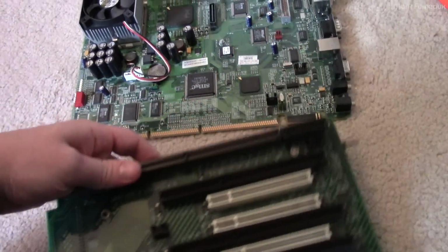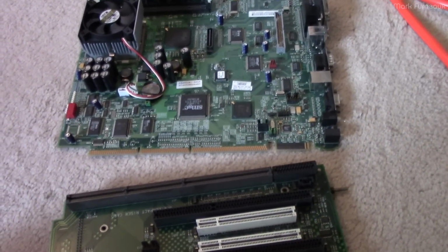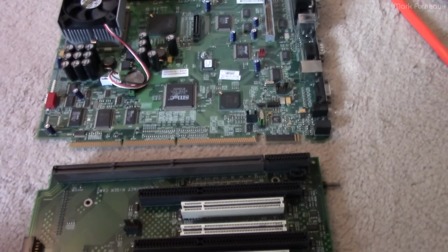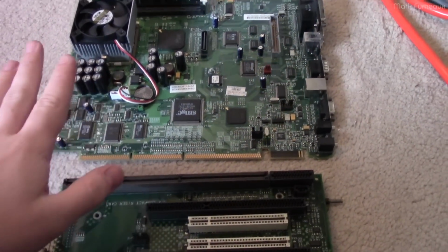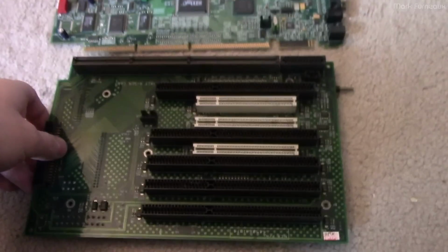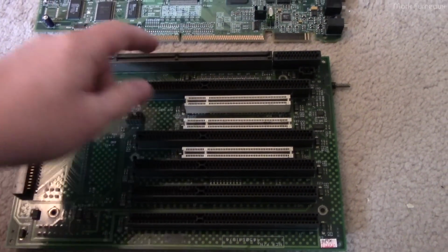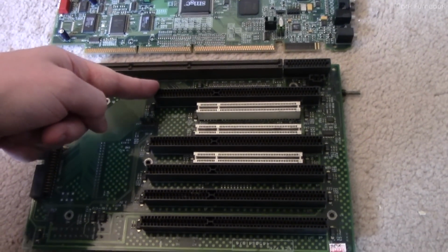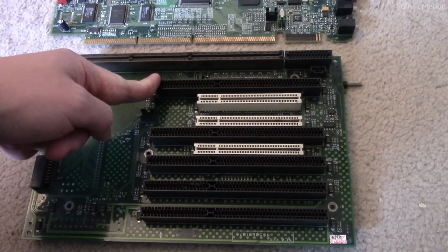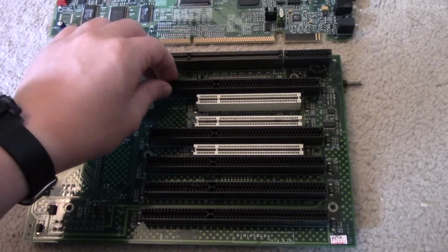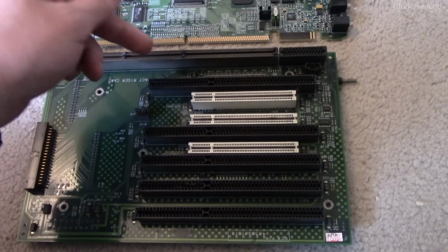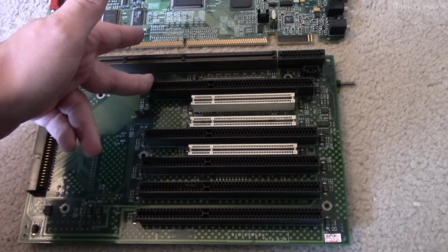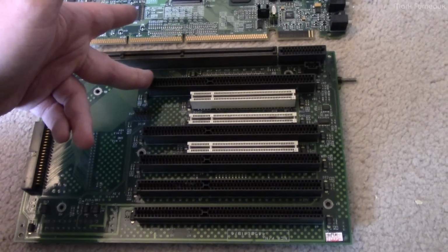But this system is from 2002, and PCI Express was not released till 2003. So this system, the Pentium 3, would never support PCI Express. And so the expansion options that we have are ISA, the Industry Standard Architecture. This is essentially the original IBM PC interconnect, which is either 8 or 16 bits, 16 bits in this case, which is a fully manually configured bus. It's just a direct data bus. So you have to set up all the interrupts and addresses and everything manually.